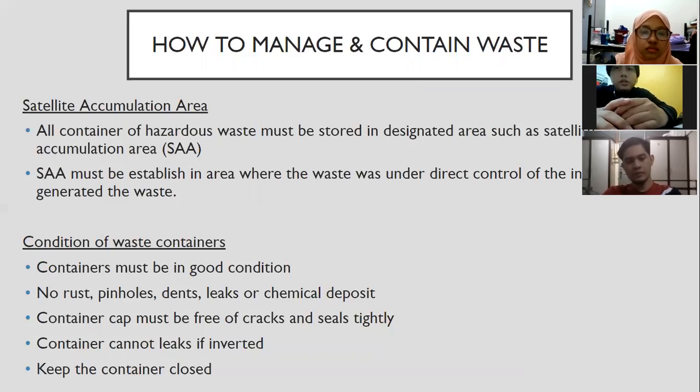So the condition of the waste container: first, it must be in good condition. Second, no rust, pinholes, dents, leaks, or chemical deposit. Third one is container cap must be free of cracks and sealed tightly. Fourth, container cannot leak if inverted. And the last one, must keep the container closed.